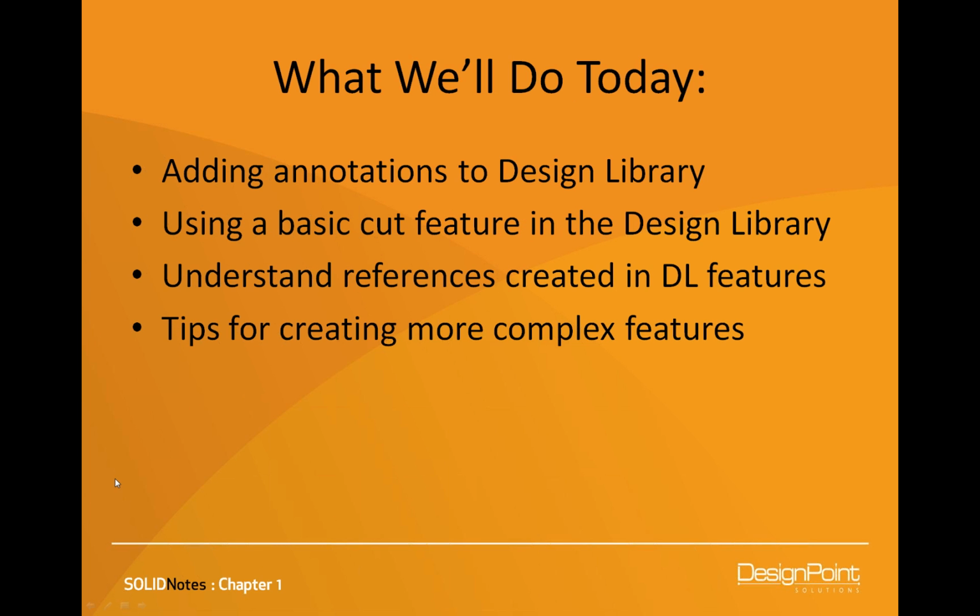All right, I'm going to give you a quick overview of what I'm going to go through today here, just kind of an introduction to working with the design library, and I'll also give you some tips here later on for more complex applications of it here. We're going to start with adding annotations to the design library, so this is applicable to drawings. And this is certainly a portion where almost all SOLIDWORKS users will benefit from it. There's a lot of reusable information when working with drawings, and we'll put those in the design library, and that way we don't have to keep recreating those.